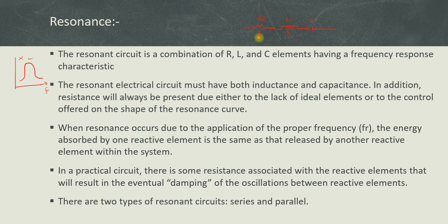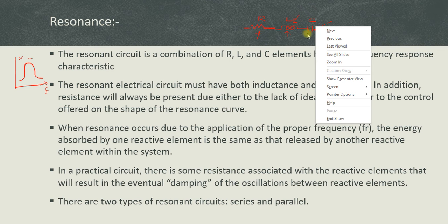When resonance occurs due to the application of the proper frequency, the energy is absorbed by one element. Here there are two elements, one is L and another one is C. As usual, the inductance absorbs the reactive energy and the capacitance releases the reactive energy, so that at resonance condition the inductance will absorb reactive energy which is equal to the reactive energy released by the capacitance.